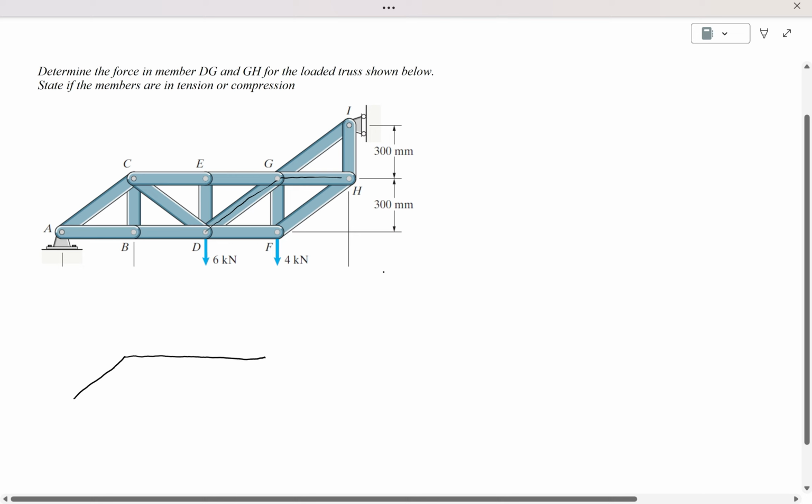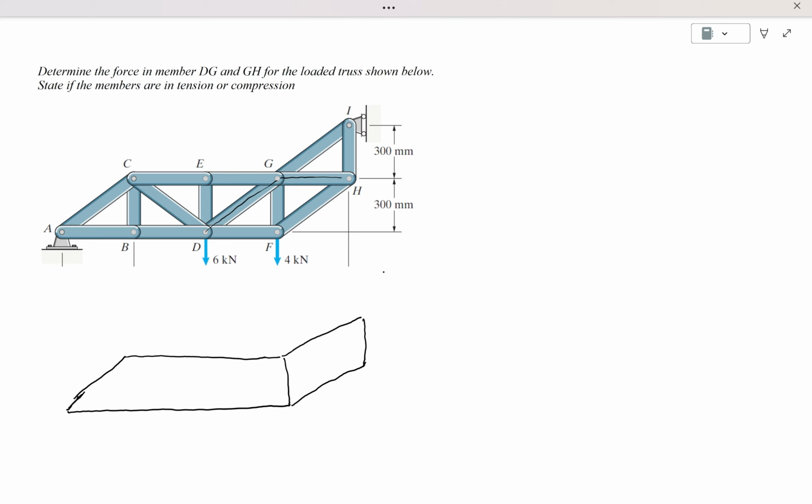I'm not good at drawing, but here you see, because you have a roller there and the roller slides on the y axis, so this is the x and this is the y, it means that it can slide in the y but not in the x, so there should be a reaction force in the x axis.